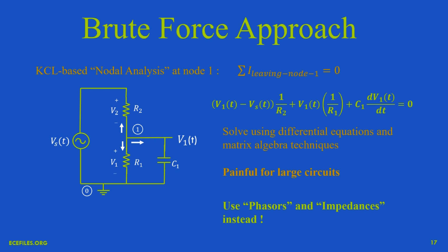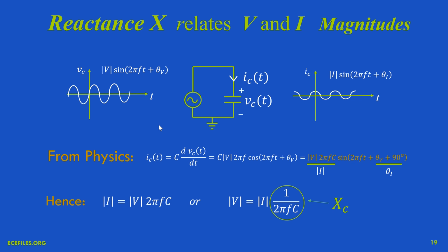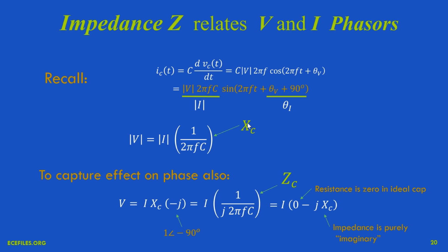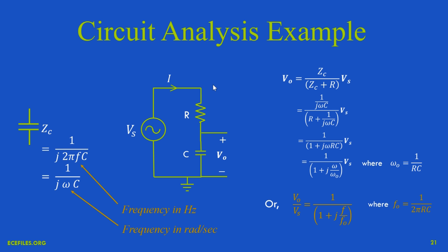Okay, take a deep breath again, because we're going to be going into some fairly deep material here. We're going to write some expressions like we did in previous episodes for Kirchhoff's current law, nodal analysis. And we're also going to take derivatives. And we're going to define things like reactance and ultimately impedance, so that we can eventually do circuit analysis and figure out what the so-called gain transfer function frequency response of this circuit is.